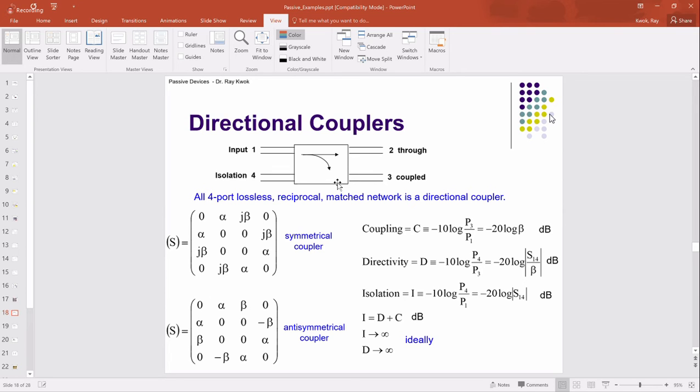So very little power, 0.1% of the power. I'm going to use that and go to my detector. So if I detect a signal, I turn off the rest of my circuit, for example. People do that all the time, right? In your phone and everything, there's always a coupler. 30 dB is typical, 20 dB sometimes, depending on what you want to do with it.